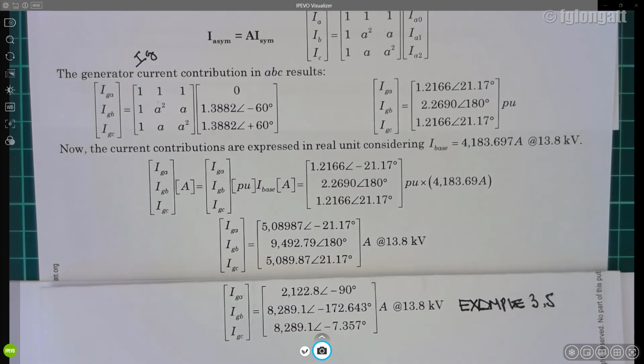Okay, and probably you are wondering what is happening there. Why do we have these changes in the fault currents? Well, the explanation is extremely simple. The phase angle changes impose a different addition when those contributions arrive at bus bar number 2.